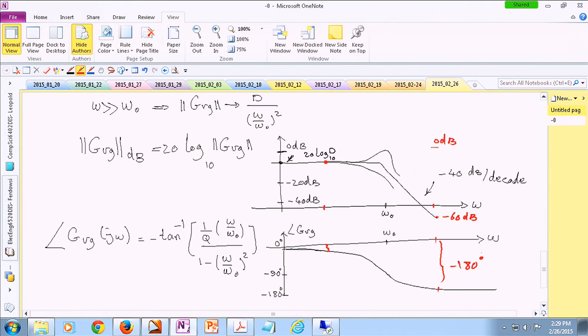So depending on where the frequency of your perturbation is, you can actually predict how the system behaves. If you are not familiar with Bode plots, I would encourage you to make yourself familiar with them, because we're going to use them a lot when you're designing a compensation network for your converter. You use Bode plots to find the best compensation network graphically. Any questions?